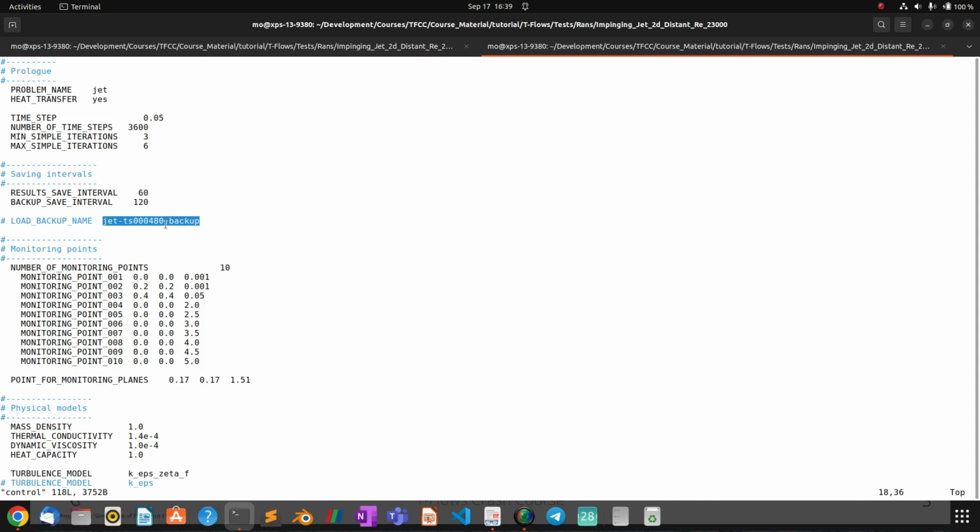when you restart the solution, you're basically starting the solution again, but from a further point in time in the flow. So let's say the solution is reinitialized by a better value than the initial value, and then it makes the solution also go faster. And then if you want to collect turbulent flow statistics or something like that, then it's definitely the way to go to decontaminate your solution.